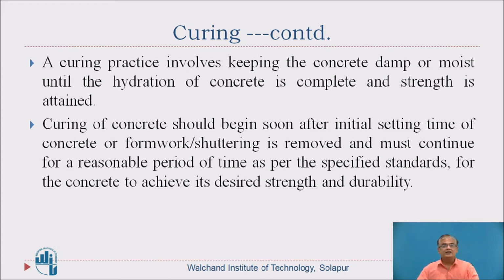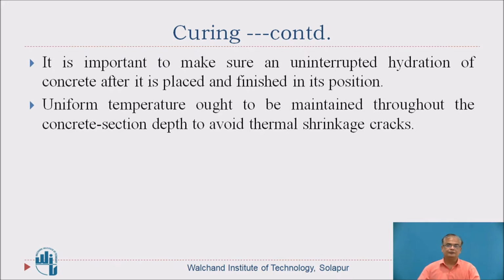When concrete sets initially, when initial setting time of concrete is reached, right? For 24 hours after initial set, the concrete is kept under 90% humidity. And after 24 hours, when formwork or shuttering is removed, the concrete is now subjected to complete curing. Water is used and other means are also there, which we will discuss now.